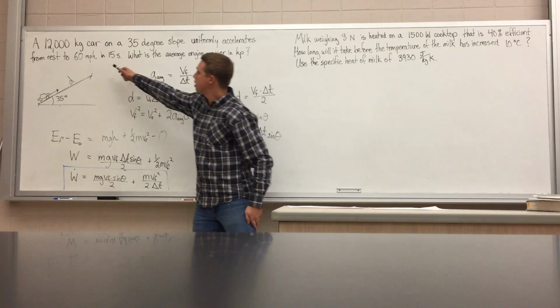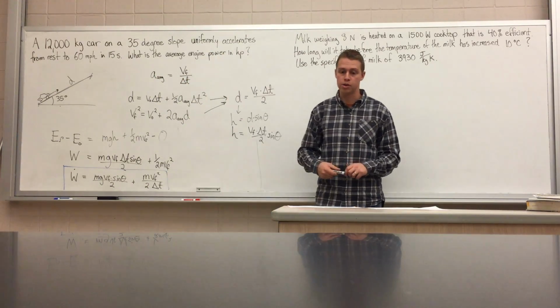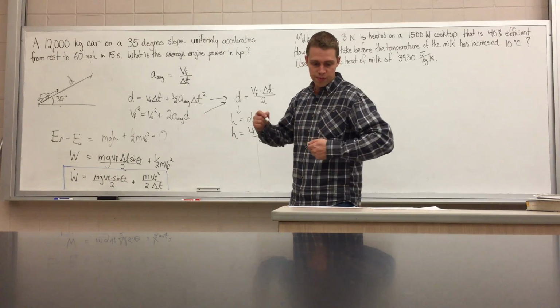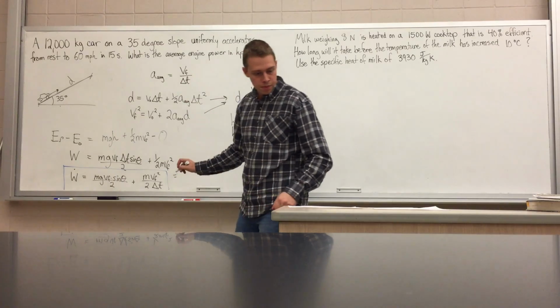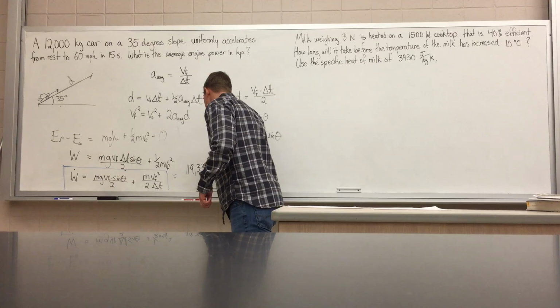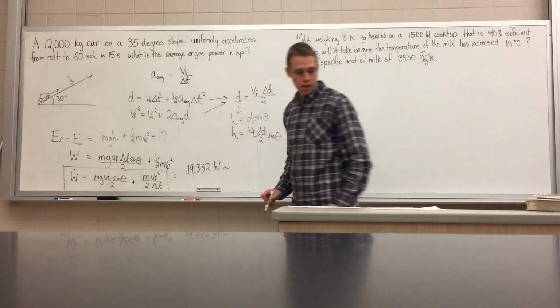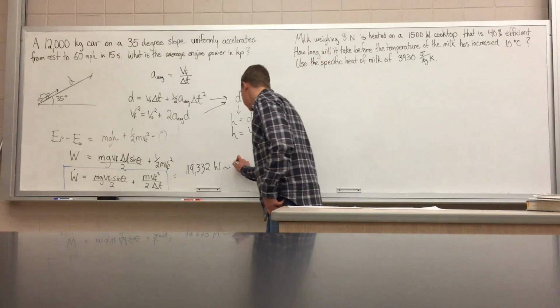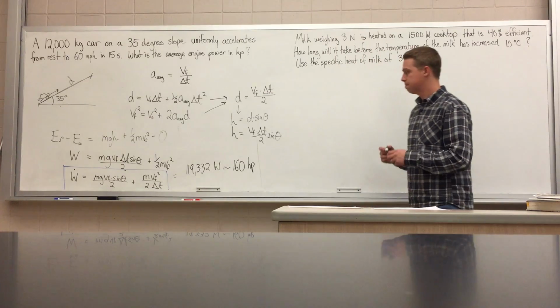And once I've converted my 60 miles per hour, that is v final, into meters per second, which is what I want, I find out that this comes out to about 119,332 watts of power, or in horsepower, like it's asking for, 160 horsepower.